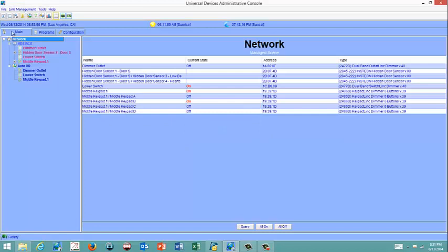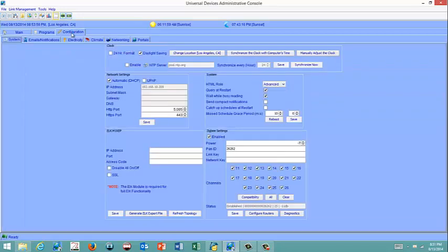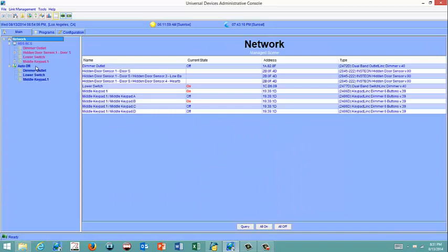Now, one of the things I want to do in this case is show how to add a Zigbee thermostat. And this is made by RCS. These are our Zigbee settings that we have set here. I don't need to do anything other than the fact that I've got the ISY plugged in, and if I want to add the Zigbee thermostat, in the case of the RCS one that we're talking about here, if you hit the menu button, it's going to highlight two blank buttons that are in the middle of your screen.